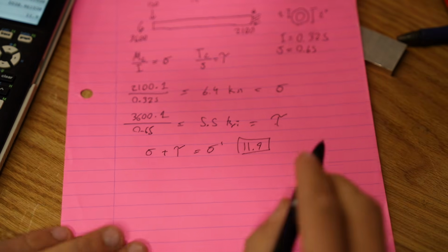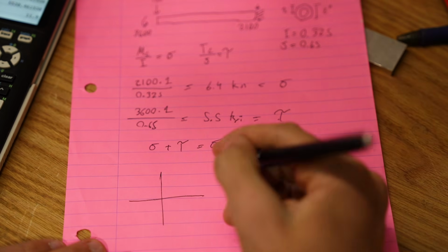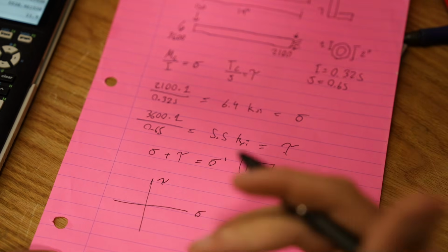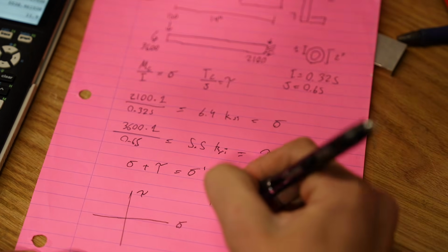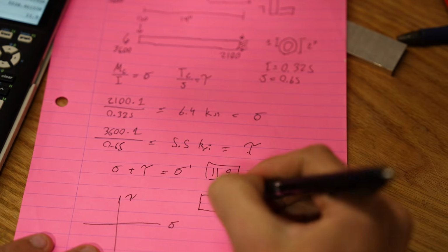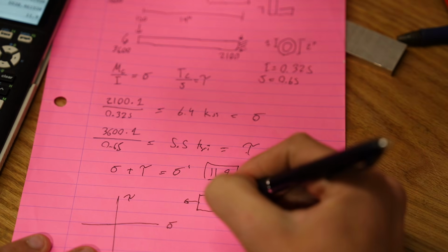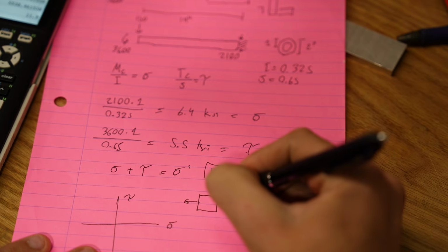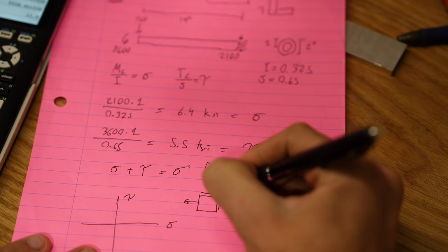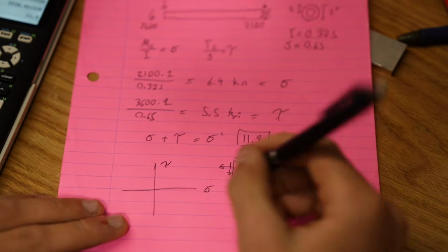The actual way to calculate this is using a technique called Mohr's circle. It's a graphical technique for solving for the equivalent stress state of a given load case. So if we draw what the very top of this beam looks like, we get a normal stress of 6.4, and we get a shear stress of, you can never remember which way the arrows go, of 5.5. I don't know if that's right, but it doesn't matter. The circle is going to work regardless.